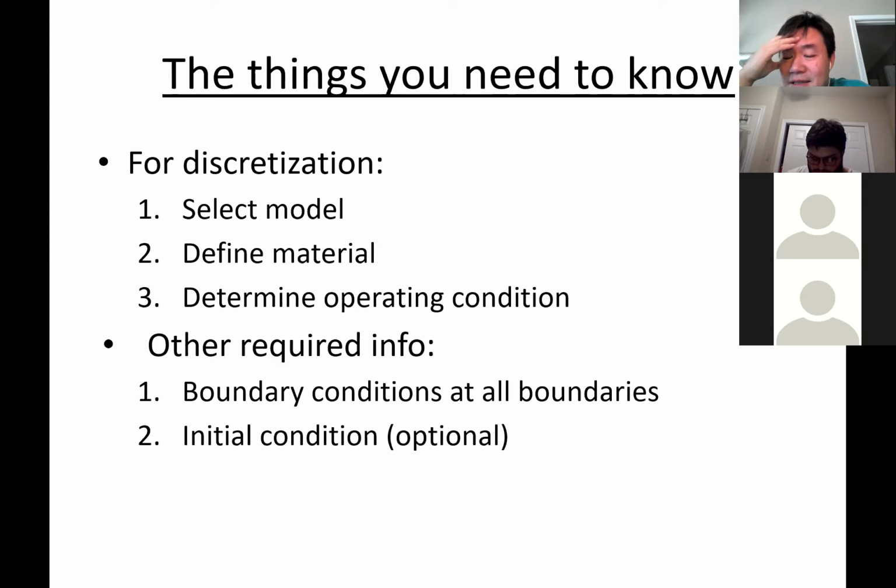Weather forecast is CFD, as I explained before, right? It really depends on today's weather for you to predict tomorrow's weather. So that's the initial value problem. Without knowing the correct initial condition is sometimes as critical as boundary conditions. This is basically the boundary condition in terms of time. If you don't have those values, forget about the simulation, because there's no hope to get the correct value at the end. Again, trash in, trash out.